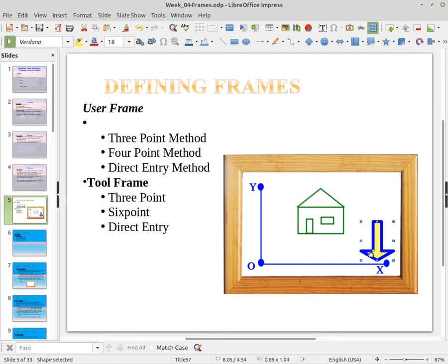If you could make it a full meter, then your points would be even more accurate, depending on the size of your robot. If you have an LR Mate type robot, one of the small ones, you definitely don't have a meter reach. But on the large robots that stand 8 feet tall or so, you can reach a long ways with them. So if you could make your points a meter apart, that'll increase your overall accuracy.